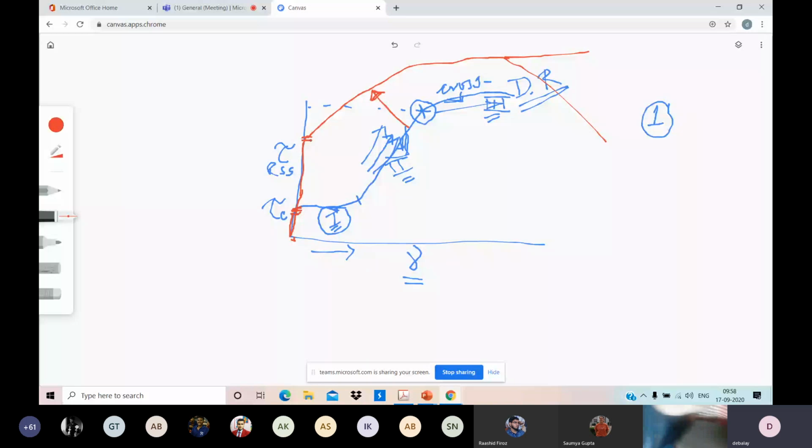In polycrystals, you will find yield strengths are much higher than the critical resolved shear stress values. So you have to understand the deformation of single crystal and deformation of polycrystal. There is some similarity and some dissimilarity. And actually the polycrystal curve will be above the single crystal curve. So tomorrow's class, please try to give me the answer.